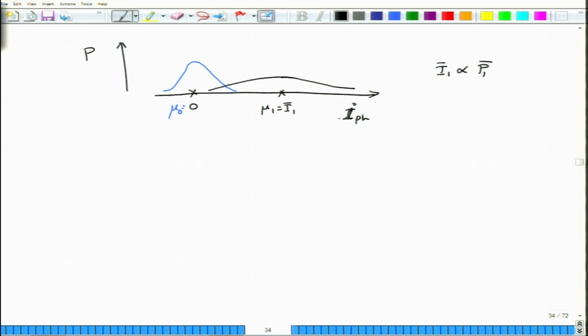Okay. So, if you have a transmitter which is very powerful, putting out a lot of optical power, then I1 will be further away on this axis, but in most scenarios this maximum value of P1 is constrained by several other factors, one of them being the constraint imposed by the laser source itself, that it cannot produce an output power which is larger than a certain maximum. So, there will always be a chance that these two tails will actually cross each other. Okay. And it is at this crossing point that you should actually locate this value of the threshold ITH.